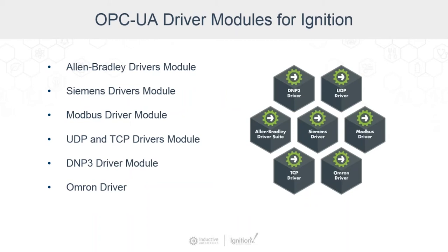Ignition has drivers for major PLC brands, and it has drivers for Modbus devices, UDP and TCP devices, DNP3 machines, and Omron controllers. In addition to those drivers, Ignition also connects to third-party OPC servers, so you can connect it to really any device. And let's just go into a little bit more depth on this because connectivity is such a critical component.